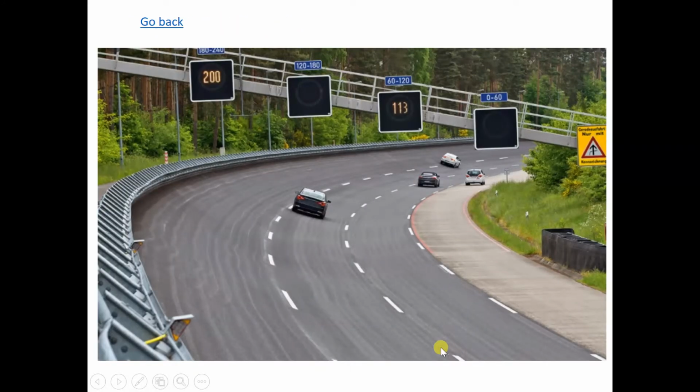So when you go around a bend, you usually need to consider the outside lane. For example, this is the inside lane, this is a middle lane, and then this is the outside lane. The outside lane, as well as all the lanes, actually need to be tilted, inclined, so as to provide the reaction to keep the vehicle from being thrown out of the curve.